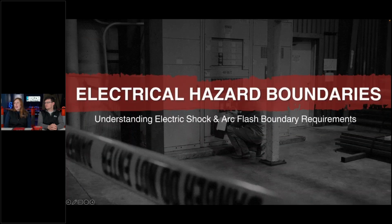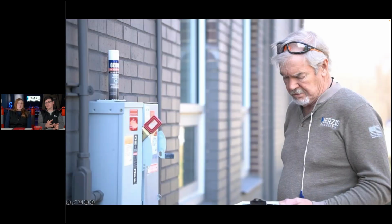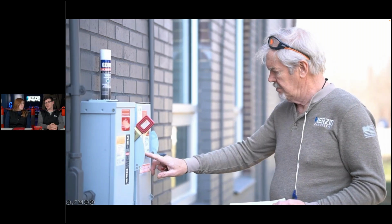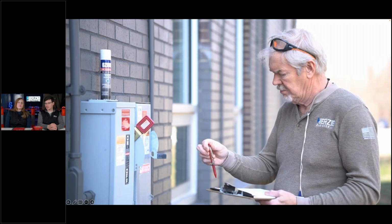Okay, so let's summarize. We're getting close to the end of the hour here. Let's summarize the electrical hazard boundaries and the generic steps ahead. So first up, plan ahead. Right? You approach equipment, what should you be doing? He's reading over the label, seeing what PPE he needs, seeing what boundaries he's going to have to set up.